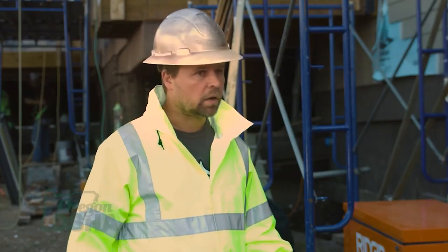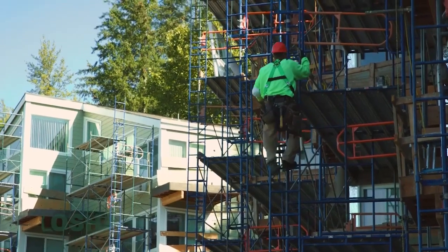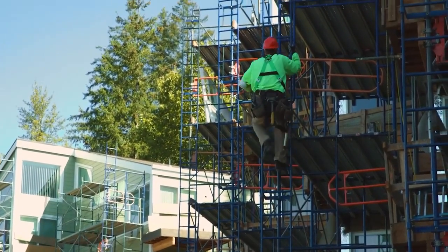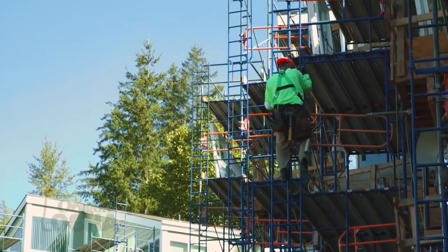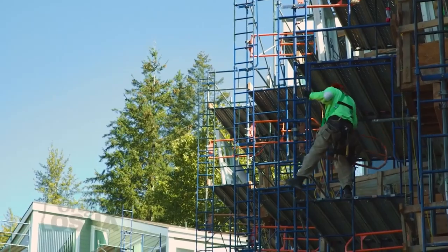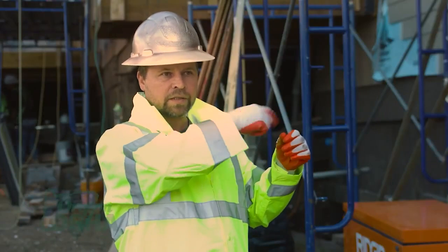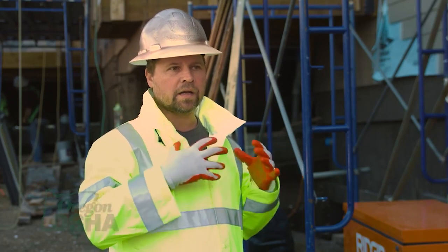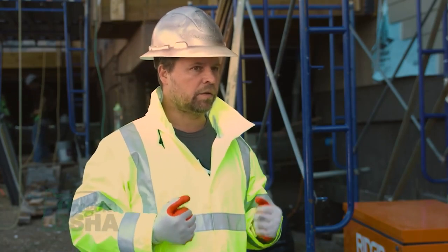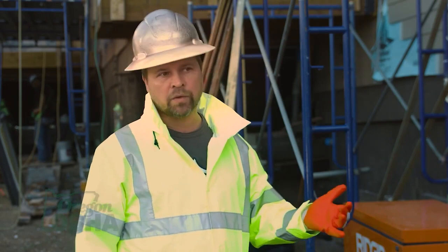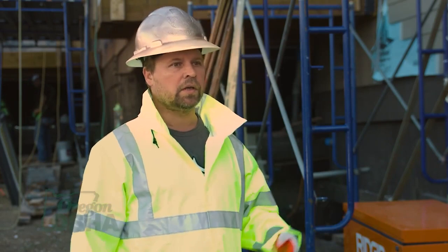We always tell the guys, hey, every time you climb on the scaffolding, really take a look at how things are set up. So obviously we do inspections pretty often, but as a general rule, anytime you climb, especially on a ladder, you want to make sure the bolts are properly secured and the nuts are all the way tightened up, so you don't want anything loose on the scaffolding. If you notice anything out of place, do not use it immediately. Bring it to the attention of your supervisor and start correcting the issue.